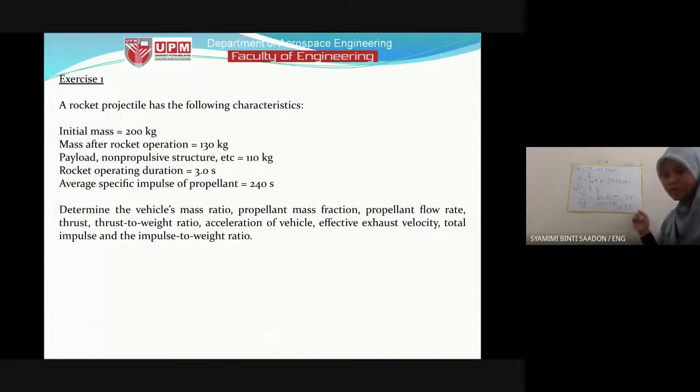So 43 for the final thrust to weight ratio. Of course the final is bigger because the velocity is at high speed after launching. So one of the important criteria is that the thrust to weight ratio increases at the final value.